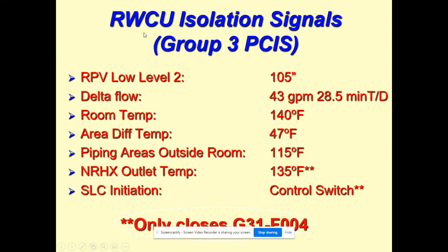So reactor water cleanup is attached to the recirc system. So it is in a way attached directly to the reactor. If something goes wrong with reactor water cleanup, there's a chance that it could be leaking water from the reactor into our reactor building, which is very bad. So if a reactor water level, RPV is reactor pressure vessel, if that water level starts to go down, we need to panic and we need to turn everything off that could be a leak.